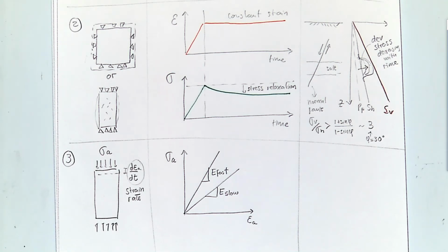If you have very high stresses, not yet at failure but high enough, you may have small cracks that propagate slowly. So if you do a test very quickly, you're not going to give those fractures time to propagate, but if you do it slow enough, those fractures are going to propagate slowly, and eventually your material is going to be softer.